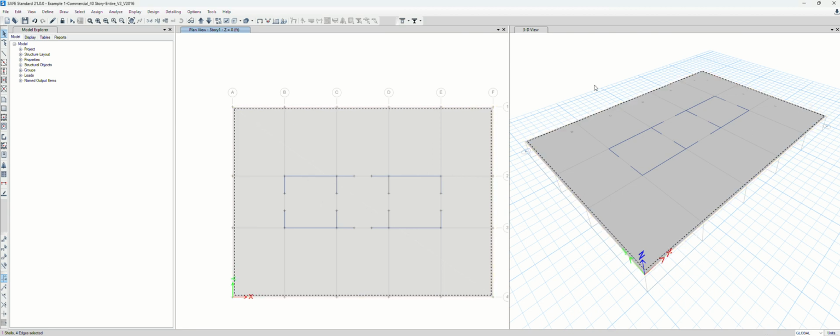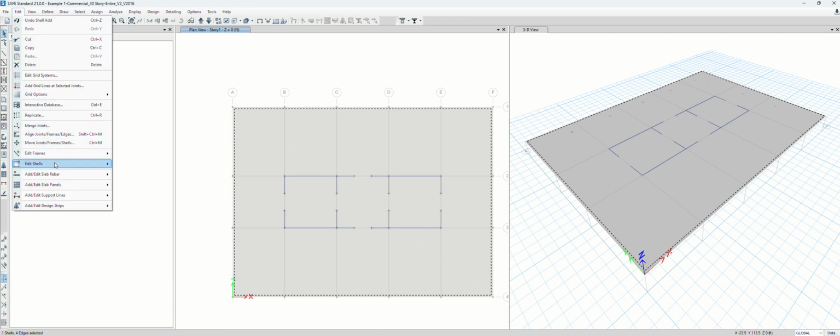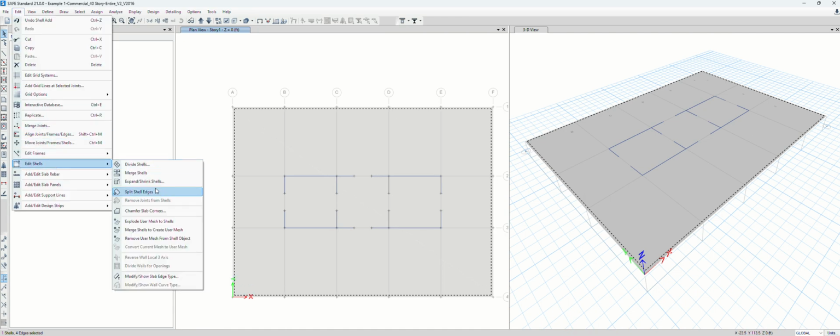The thing is, you see that because this is column location, practically we can't put the column on the edge of the mat. The mat should be bigger, right? Like a base plate or column spread footing. So what we need to do is, geometry wise, we're gonna extend. So expand. So go to shell. Here, expand the shell.